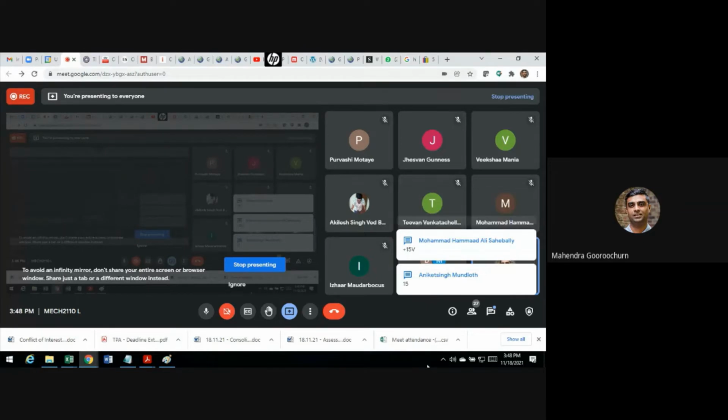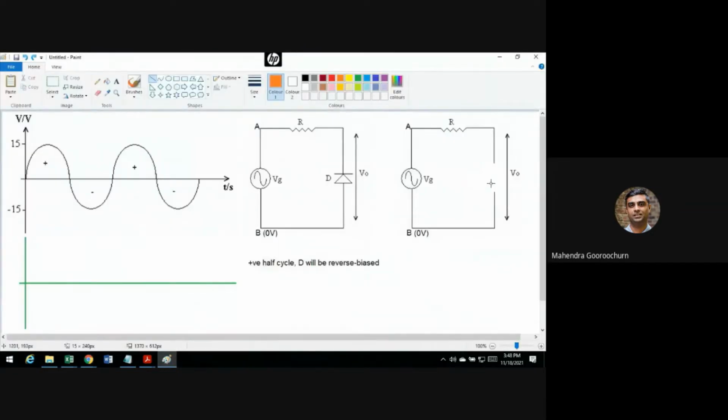So most of you have said 15 volts till now. For those who are not sure, let me explain the thinking behind it. If you don't have any current flowing, you don't have any drop across the resistor, because the resistor needs current to have a drop. The moment there's no drop there, the full supply appears across the open circuit. If you were to connect a voltmeter here, you would simply measure the supply.